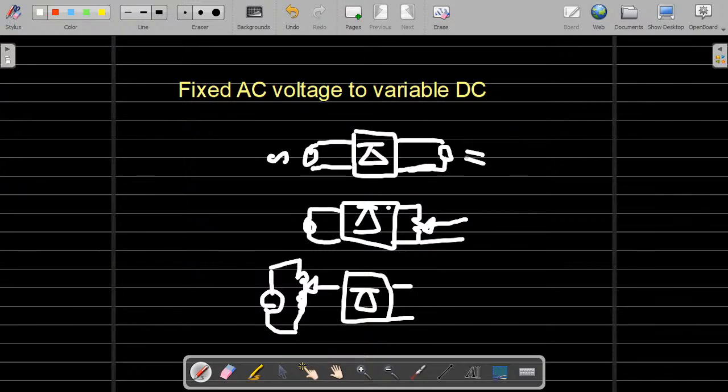There is a continuous power loss in that potential divider, so this is not efficient. Then if the current rating is very high, then the potential divider will drop more and more voltage. Okay, there is a heat loss in that resistance. So again, not much practical.